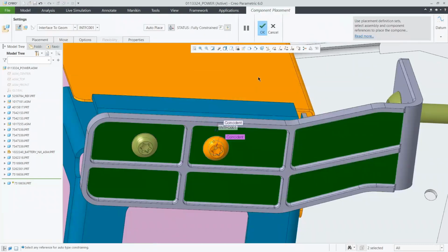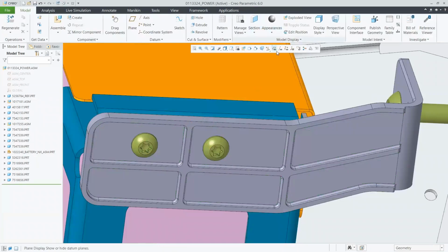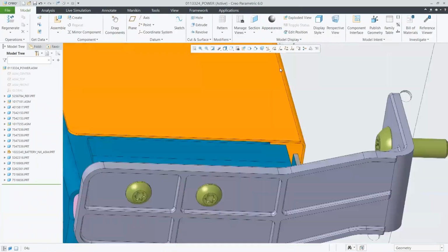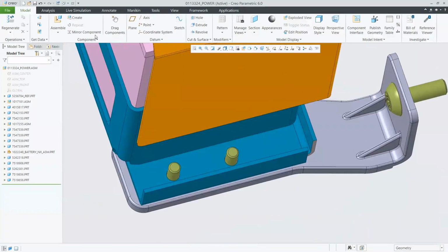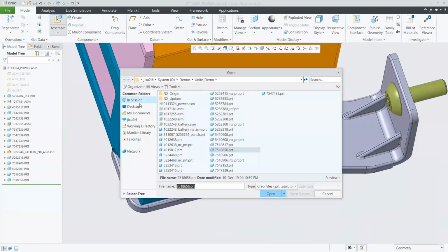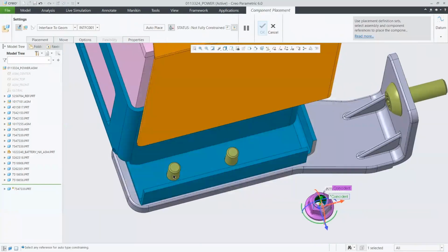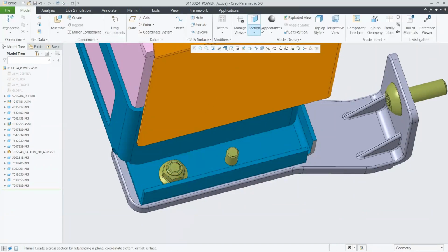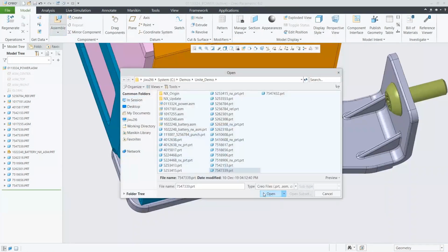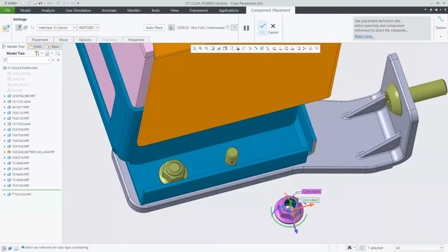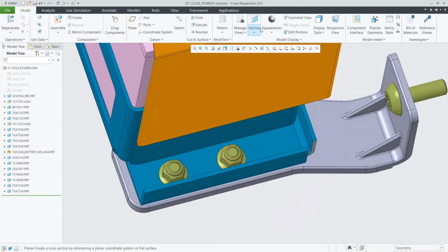What it really does is, in a couple clicks, you select the fasteners you want. Say you select a bolt, it will recommend to you the correct sized washer, lock washer, and nut that are going to fit that bolt. It gives you a preview as you're laying it out so you can verify that what you're selecting is correct. And then it will also examine your model and say, there are 10 other instances where you could put this exact fastener. Do you want to put it on all of those instances or just this one?